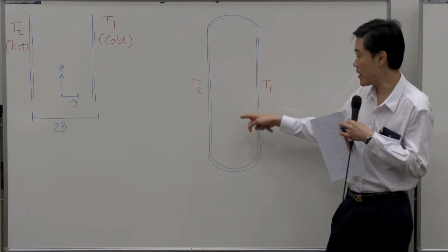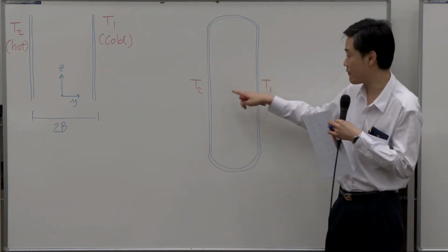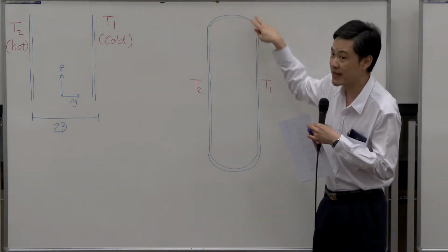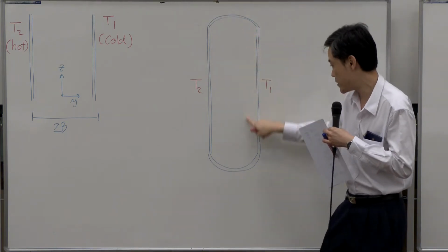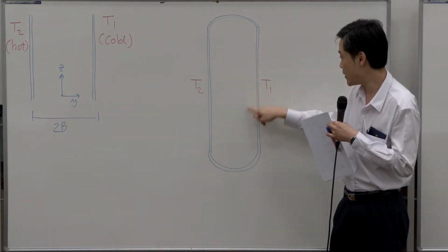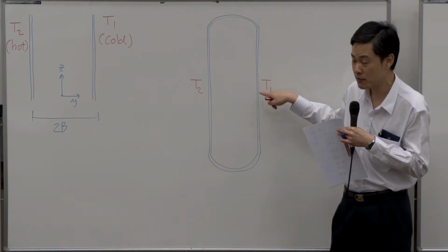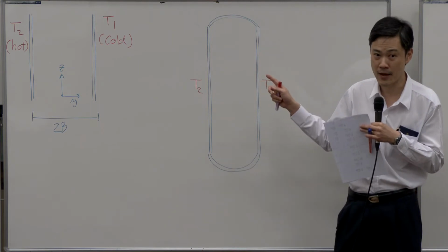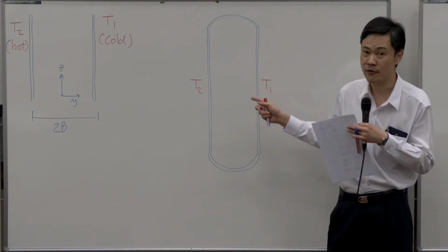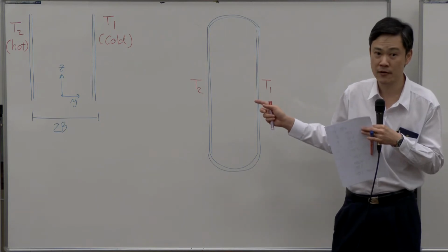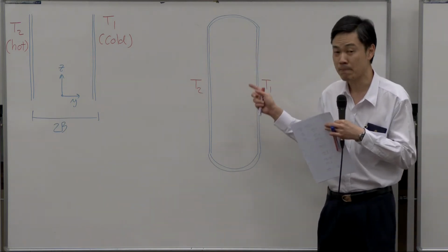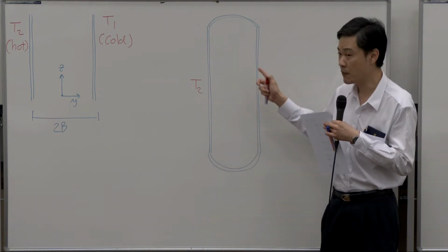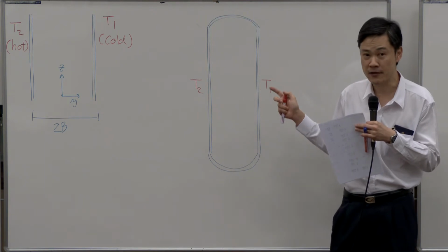Okay? So there will be somewhat of a circulation of fluid. Hot fluid goes up here. If this part is not heated, it will cool down and recirculate back there. When it's down here, it's touching the cold wall, the density sinks down here, and it's recirculated. Okay? So this is what we call natural convection. There's a movement of fluid, but not by an external force, not by gravity, but the movement is caused by differences in density.